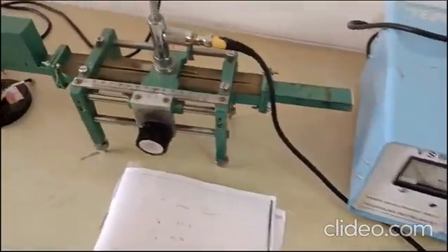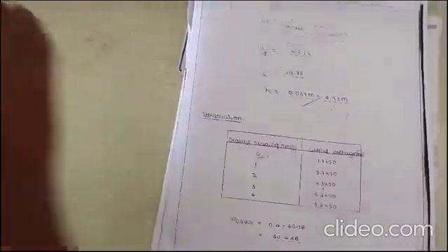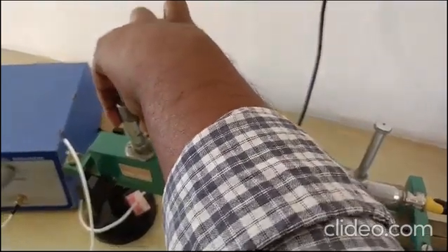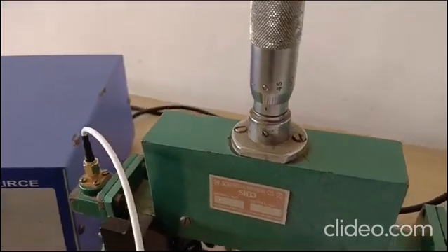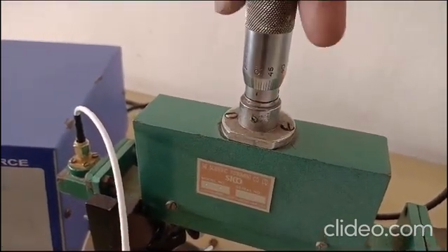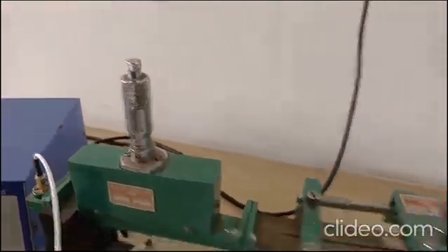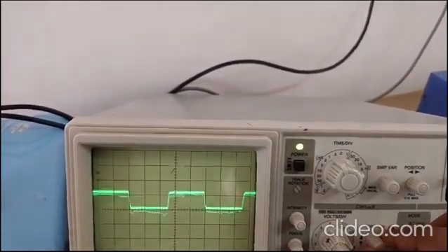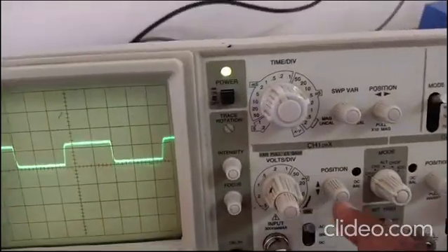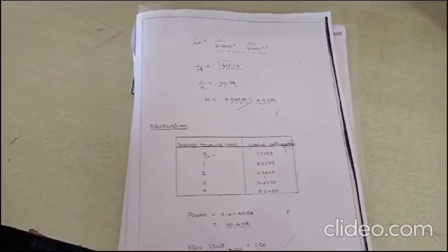At that time, just vary this attenuator for one rotation. You have to find out the attenuation. For the first reading, you rotate for one rotation. For the second reading, you took the reference as 0 here, and then you rotate one rotation again and you got the same value 0. You should rotate in the anti-clockwise direction so that you can observe the voltages here. Just adjust here, that is 1.2 multiplied by 20 millivolts to get a value here. That is the first reading. Similarly, you have to find the remaining readings the same way.